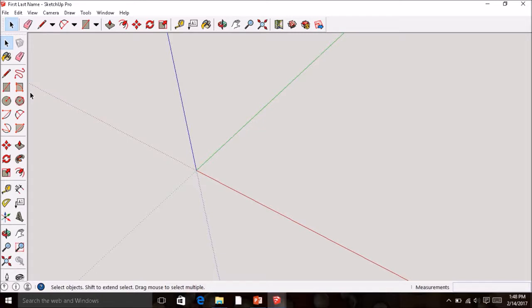Our catapult is going to be made of 3/4 by 3/4 inch lumber. So we're going to use that as our sizes as we go. We're going to start by moving over, and you'll see how it tells me I'm going to use the rectangle. And I'm going to come down here and start moving it off to the right. I'm going to draw a small rectangle that's going to be 3.5, comma 0.75. And I'm going to hit enter.